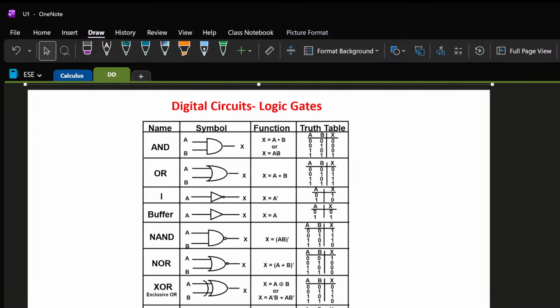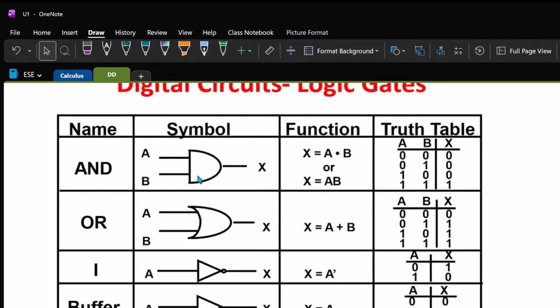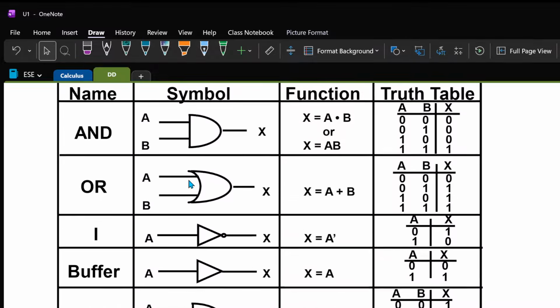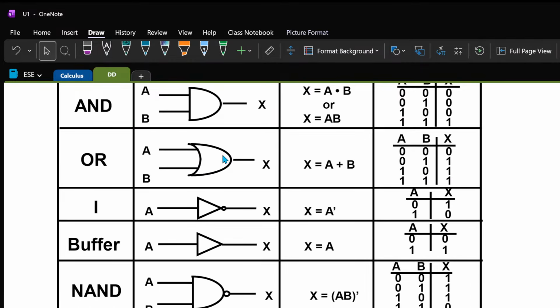Yeah, and you have all these gates, AND gates. So simple logic of the gates. With an AND gate, you'll get many inputs and you will get one output. Whatever inputs you're getting, you will see if even one of the inputs is 0. If even one of them is 0, the output will be 0. Else the output will be 1. Or to put it in other words, only if all the bits are true, it will return 1. Else it will return 0. Similarly, for OR, if even one of them is 1, it will return 1.